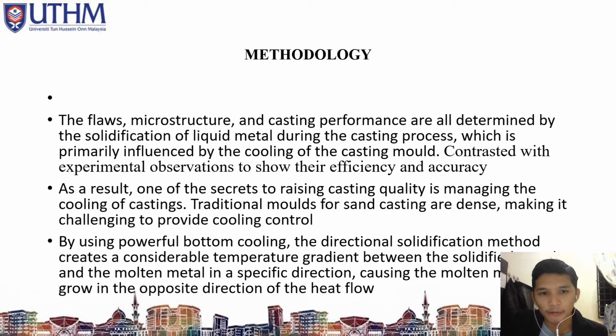By using powerful bottom cooling, the directional solidification method creates a considerable temperature gradient between the solidified metal and the molten metal in a specific direction, causing the molten metal to grow in the opposite direction of the heat flow.